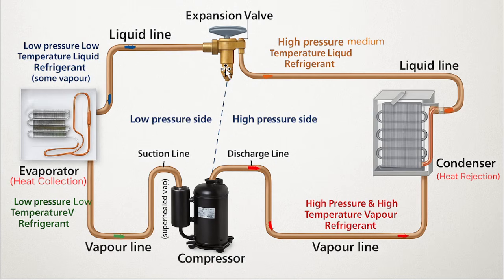I think you may have already gone through this Joule-Thomson effect. There is one experiment where real gas is compressed from the high compression cylinder to the low compression cylinder through the throttle. So when the gas escapes through the throttle and then suddenly expands, the cooling takes place. So this expansion valve actually carries the principle of the Joule-Thomson effect. There are some capillary tubes, so the liquid gets into the smaller capillary tubes, and suddenly when it opens into the bigger pipe, expansion takes place.